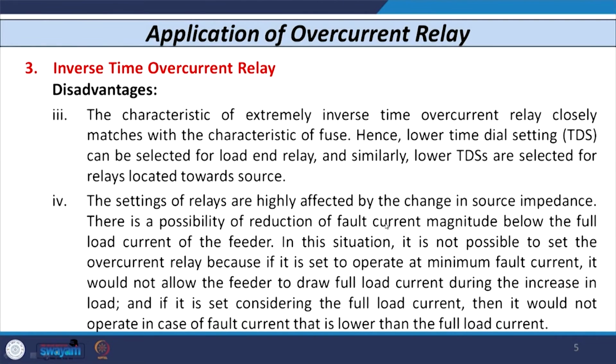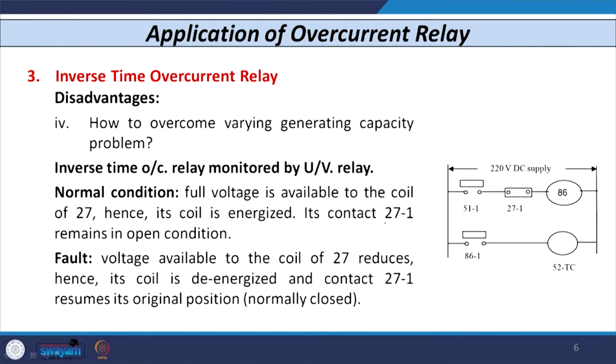So, to avoid this, the solution is that we have to use the overcurrent relay that is monitored by an under voltage relay.